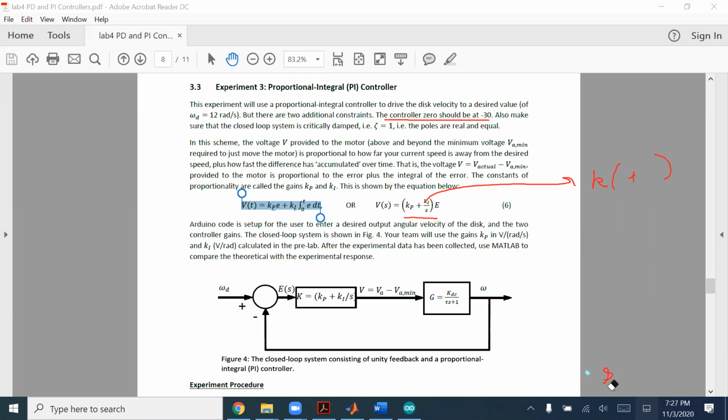So the derivative, like in a PD controller or the PD controller with an extra derivative filter in it. So the derivative is really easy. Derivative is basically current error minus previous error divided by delta t. But integration is going to be interesting.